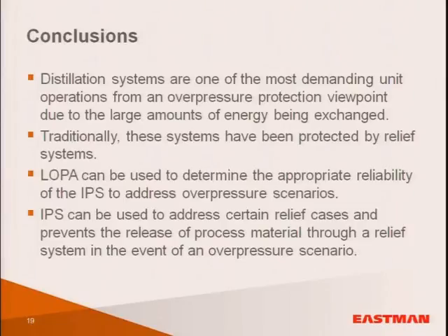So we looked at those various approaches, and those are written up in the paper as far as our thought process moving through. But we determined that the instrumented protective system could be effectively used on distillation systems, particularly to address certain relief cases, preventing us from having to relieve those and deal with the effluent handling situations, as well as minimizing the size of our relief system. So we did look at several approaches, but determined that the instrumented protective system would be very effective in this case.